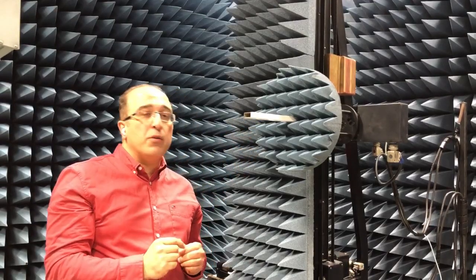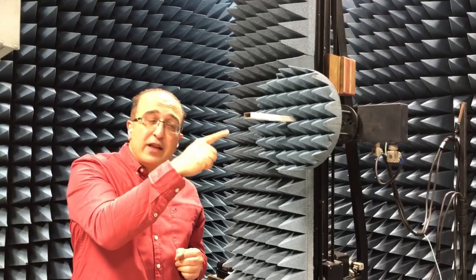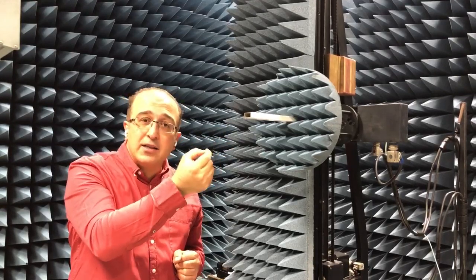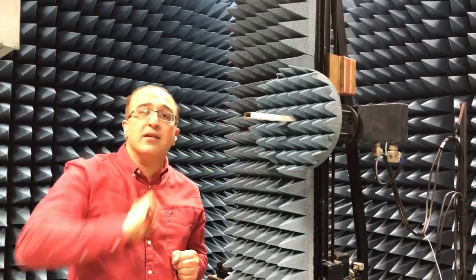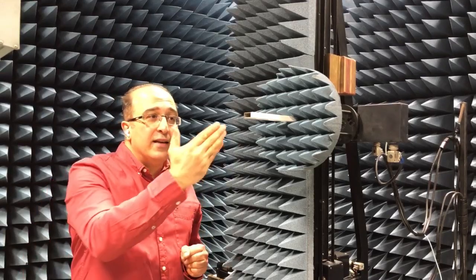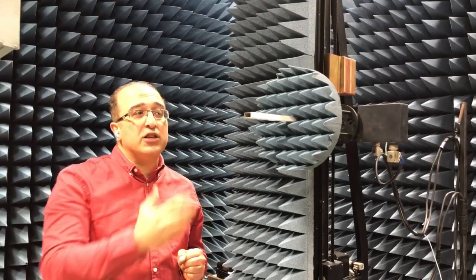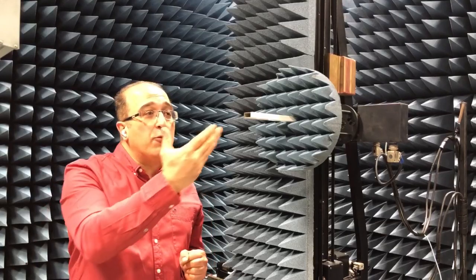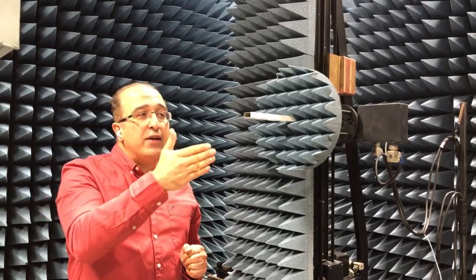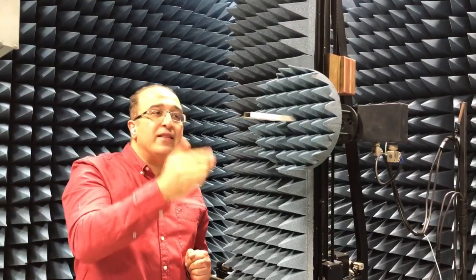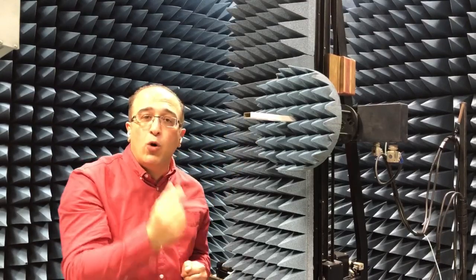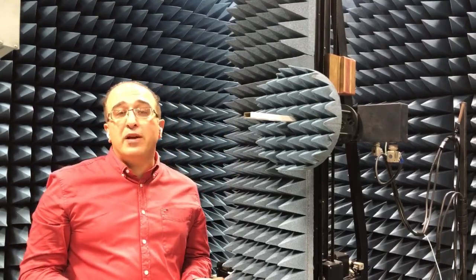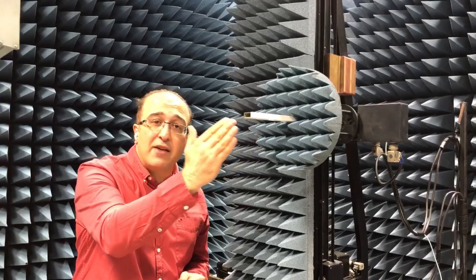So the electromagnetic wave from the back is fed to this system by a coaxial cable, and then electromagnetic waves travel in this structure, which is open-ended, which is a waveguide antenna. So this waveguide can guide the wave, and then if you leave the end of it open, it essentially becomes an open-ended waveguide, because when the wave is traveling through this waveguide, the electric field has a distribution.